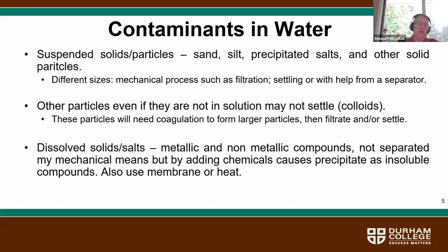Membrane technology is out there and is actively used in the industrial sector as well, typically ultrafiltration membranes. So they're membranes with very, very small pore diameters. The wastewater is pumped into the membrane system. Water passes through the membranes, but the dissolved solids, because of their size, will be blocked by the membrane, and they remain on the dirty side for recovery.